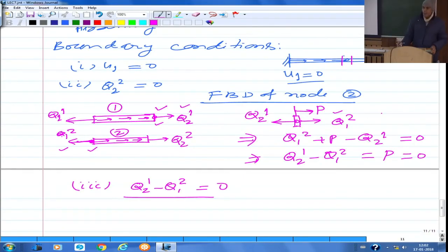It is very important. As far as accounting for this external force is concerned, you can simply, if this force P is along the positive u direction, directly add it at the corresponding node row, that is the second row in this case because it is the second node.